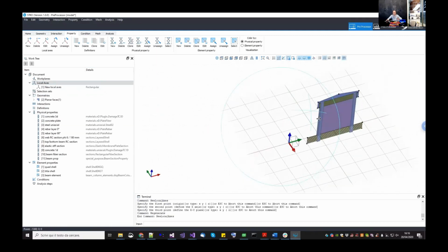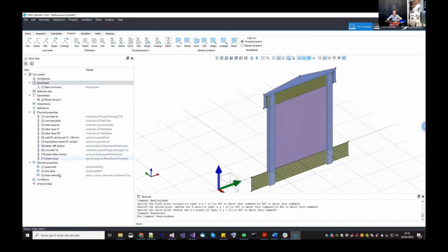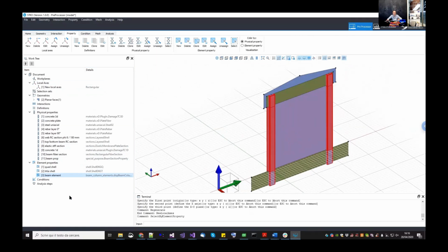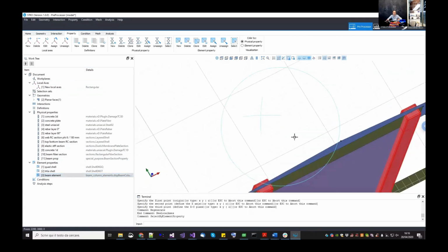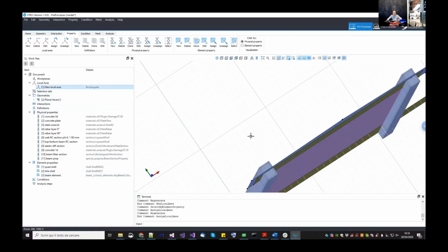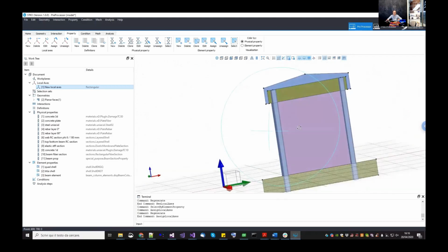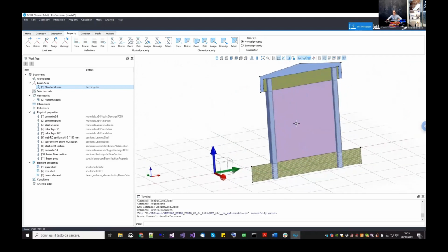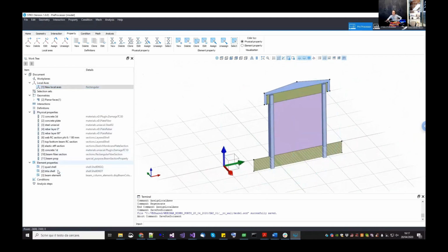Okay, so that now I can select my material, my entities where I assign the beam. So select, and I can simply drag and drop this one, and you will see how they will rotate. So I drag and drop this new local axis. Okay, now they are oriented in the opposite direction. Okay, so we can save this one because we are done with the geometry, constitutive modeling, and element properties. Now we can go to boundary conditions.